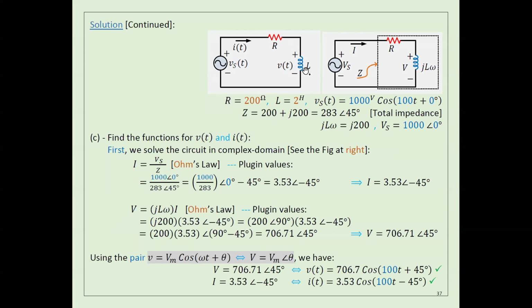For example, if I ask you to give me the voltage here, and I give you this voltage, but I need to know the voltage here. Can I use voltage division? You know what I'm saying? So now to solve this problem, similar to what we did before, there are two ways. One way, as I did here, you can get the total impedance, and then you divide V by the total impedance. Once you have I, you just multiply I by the Z here, that's it, you are done.